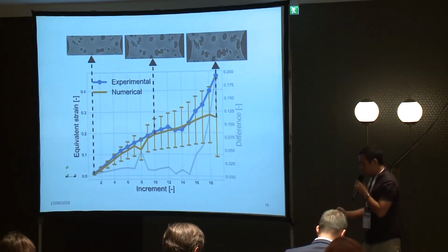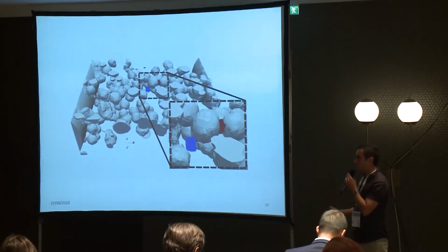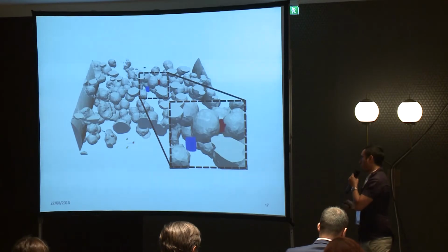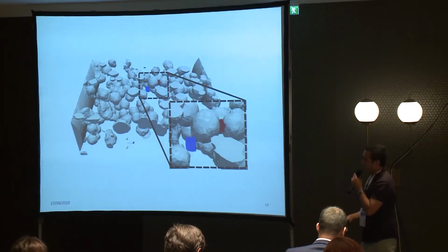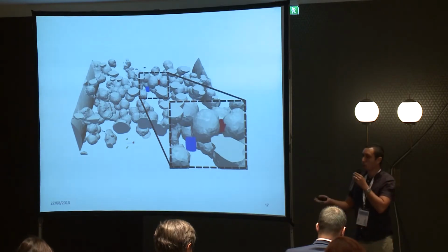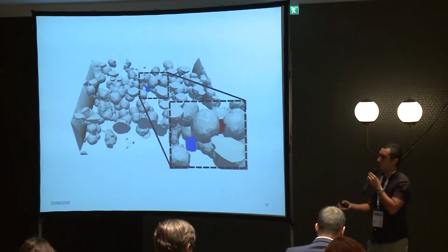And the reason why we have these bars here is that if we go back and take a look at the probe where we are seeing the strain, this probe is in a very small intervoid ligament, and it's big with respect to the ligament. So one portion of the probe will actually be inside of the void phase. And why did we do it like this? We did it like this because we are trying to validate our results by comparison with the DVC. And the shape, location, and size of these probes actually correspond to the geometry of the DVC elements.